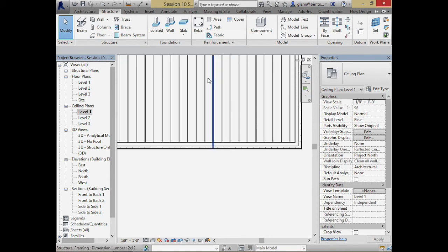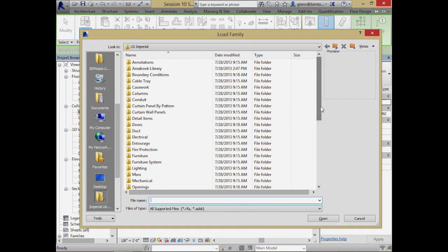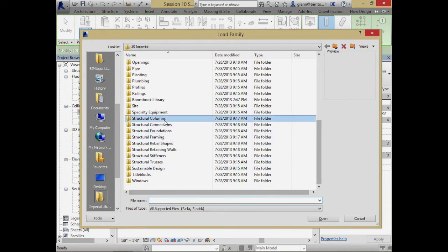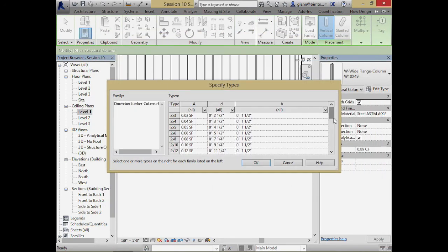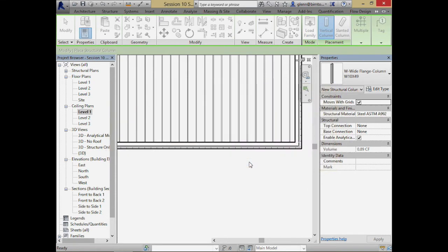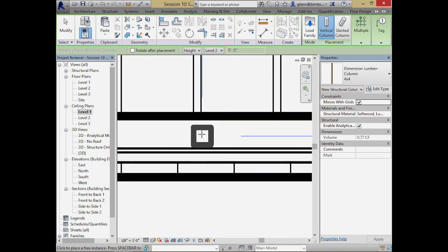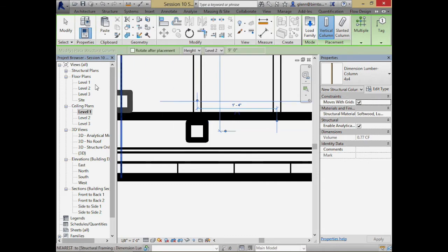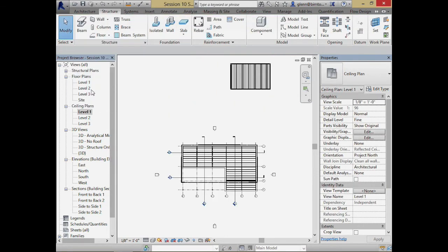We'll go through and put a structural column. So we'll say a column, but instead of a big old steel column, it'll be more, okay, a structural column there, wood, dimensional lumber. Very common in a lot of the work I do, we use 4x4s or 4x6 columns just to support beam loads that come on down. So we'll go through here, and in the framing, we'll put a structural column just right at the location where, zoom to fit, that is.